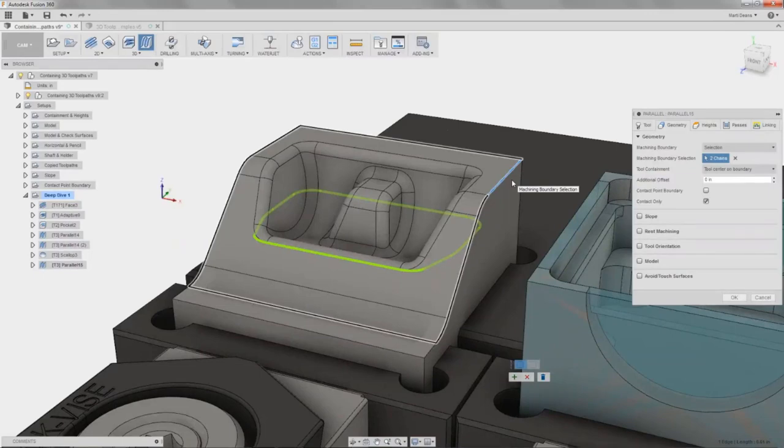So Fusion is kind of assuming what I want. So to edit this, I can just make another selection. So now that one's also blue, and the black line's updated to include that in the selection. I could also, like, if I wanted it out of this upper part, nope, okay. So now it's including the whole part, including this bottom face. I'm good with that. So I'll hit accept to save my changes.